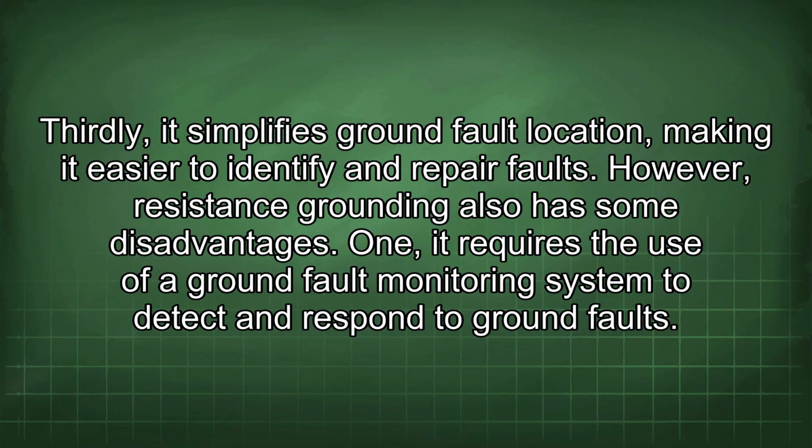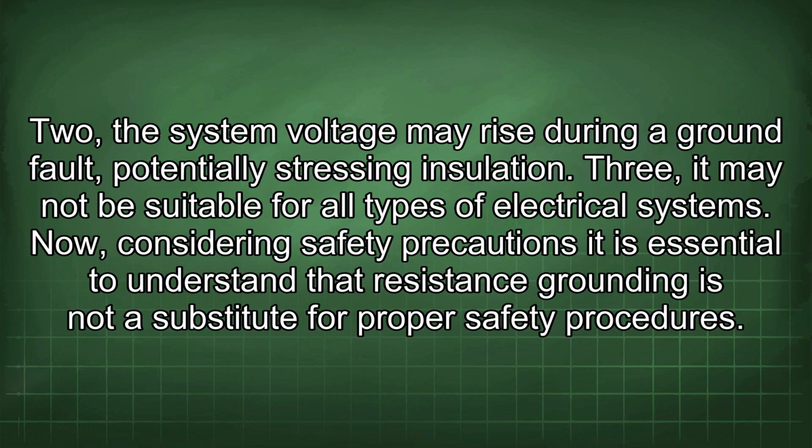However, resistance grounding also has some disadvantages. 1. It requires the use of a ground fault monitoring system to detect and respond to ground faults. 2. The system voltage may rise during a ground fault, potentially stressing insulation. 3. It may not be suitable for all types of electrical systems.